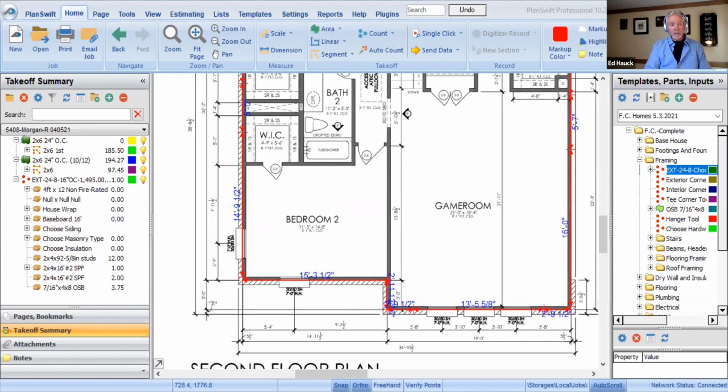Exactly. We've tightened up the lumber list. If we send out a big fat pile of lumber, they're going to use up all that lumber and blow through it pretty quickly. So again, it's just getting that information out, getting good details on the plans, and the education process. The first couple of times you really tighten these things up, you're going to find that the framer has to work a little harder.